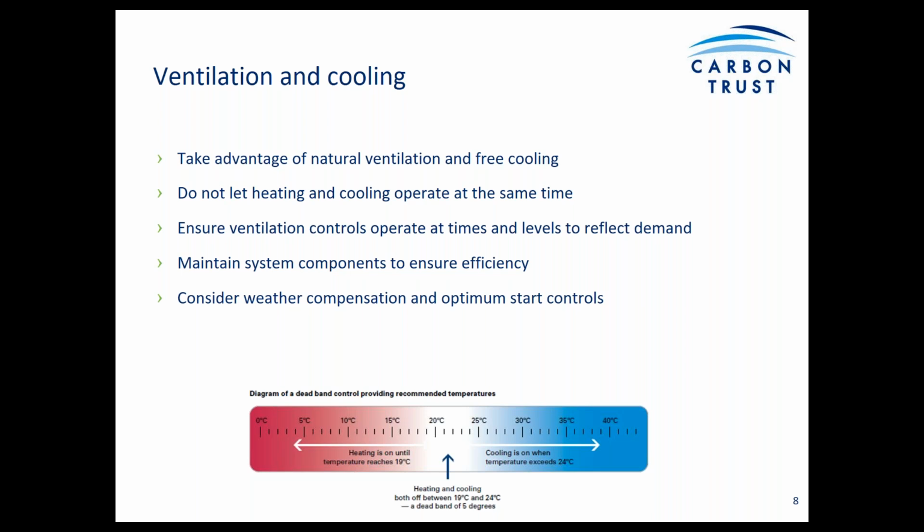Many charitable organisations are housed in older buildings, and these typically have a large amount of air infiltration through, for example, floors and windows. So they might not require any additional ventilation to the natural ventilation that already exists. In fact, some areas of these buildings can be quite excessively drafty. And so draft proofing and weather stripping can be quite beneficial in terms of reducing energy bills in these businesses, as well as reducing things like dust and noise levels.